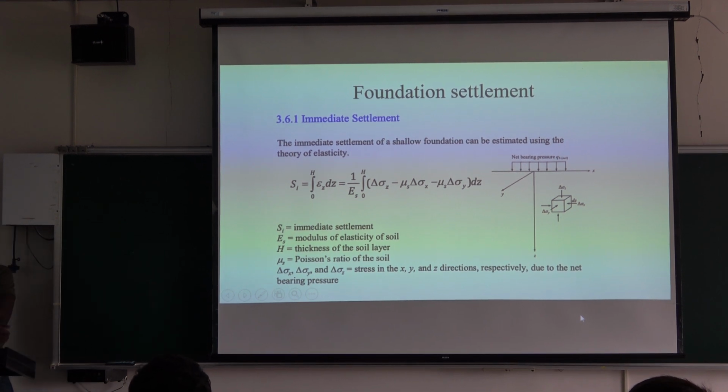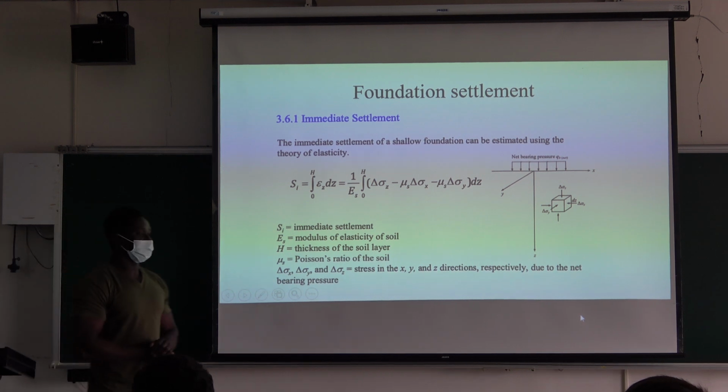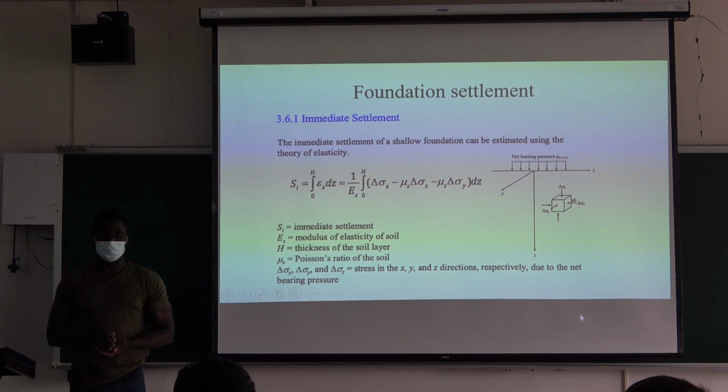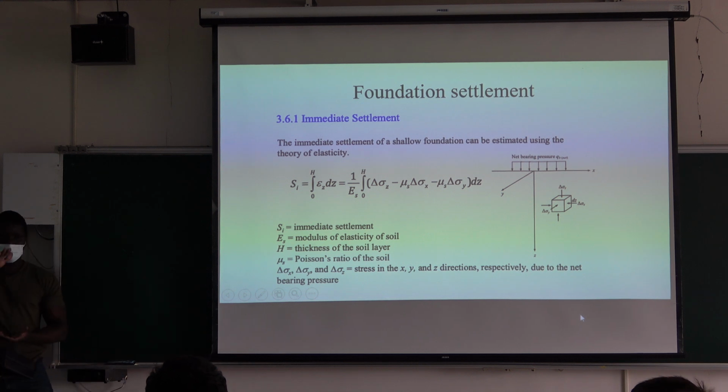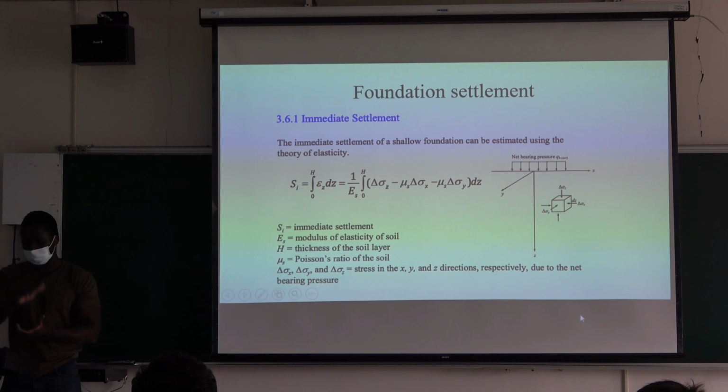For now we will focus on the immediate settlement, the settlement that takes place immediately when you finish construction. Because you are applying a load to the soil, and the soil will behave like an elastic material. When you apply a force onto it, it will definitely compress, or settle.